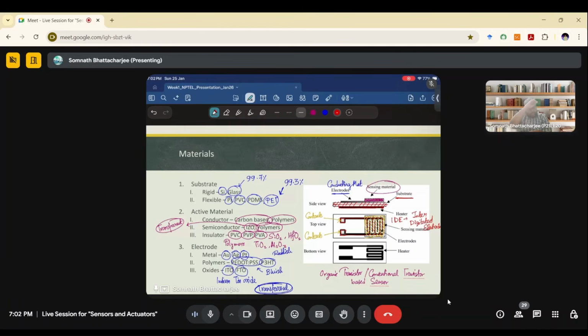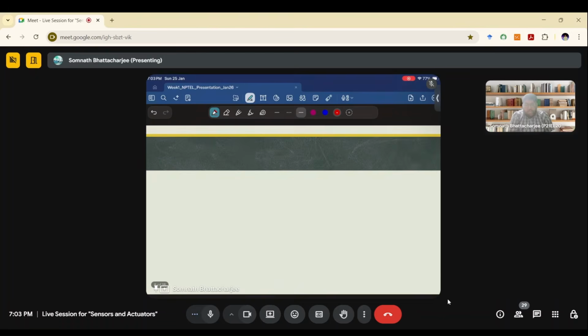So let's say there are several sensing parameters. You can say that my sensor is very accurate. Someone can say my sensor is very precise. And based on your use case, you need to think about whether you need a more accurate sensor, whether you need a sensor with a huge range, or it is enough to have a very small range, and whether you need a very precise sensor or something like that. So based on your use case you need to choose the materials, you need to optimize the process flow of this sensor fabrication, and also utilize a specific equipment which is also in your budget as well. So now we'll move on to the questions for this.